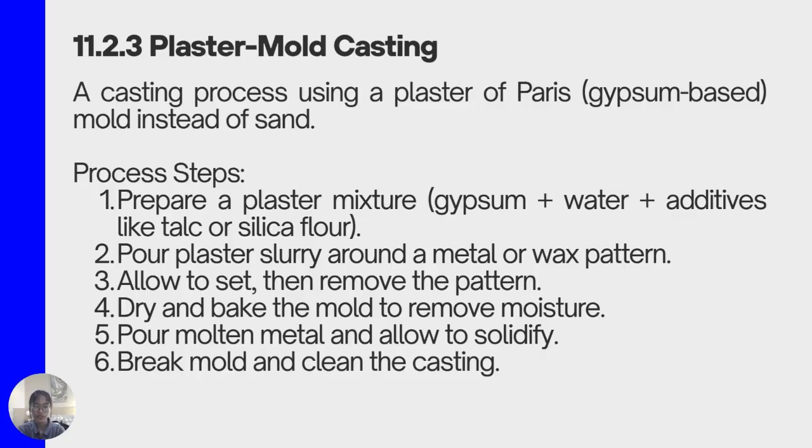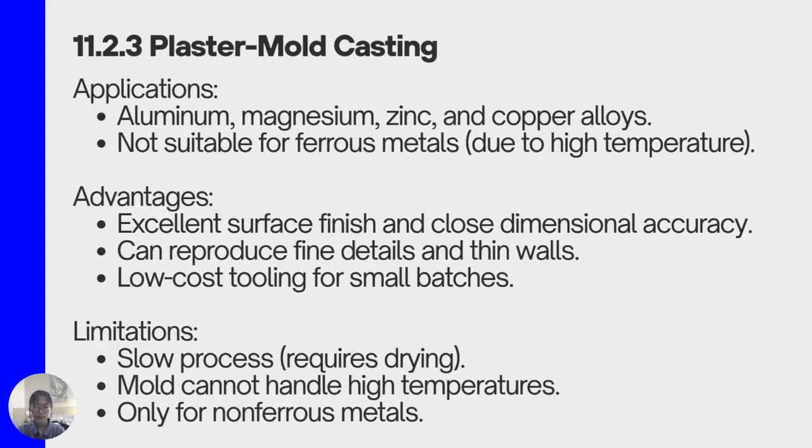Typical applications for this include fine details and smooth surfaces, such as aircraft parts, pump housings, and decorative items. The main limitation is that drying time and mold handling make it slower than other expendable mold processes. And these are the applications and advantages. The advantages include excellent surface finish and close dimensional accuracy. It can reproduce fine details in thin walls, and it is low-cost tooling for small batches.